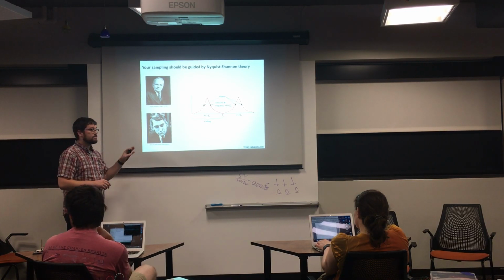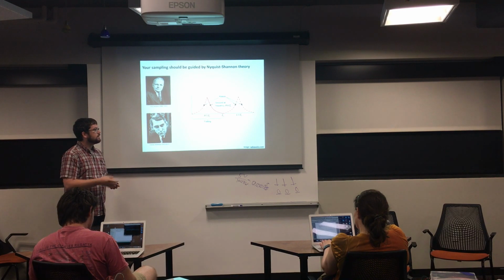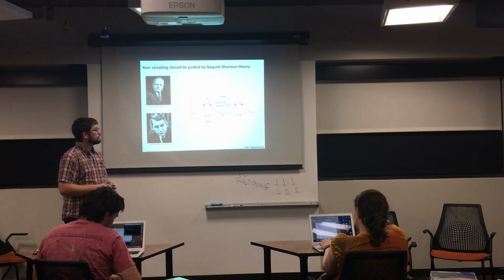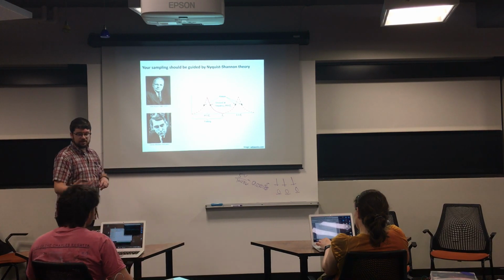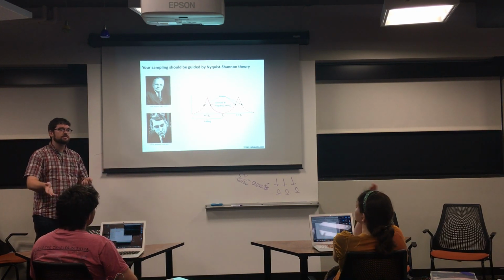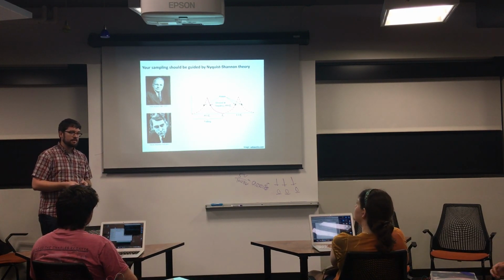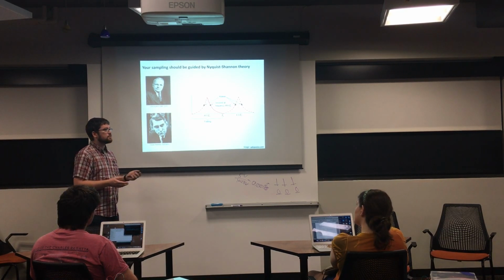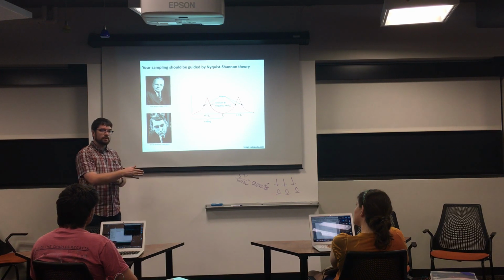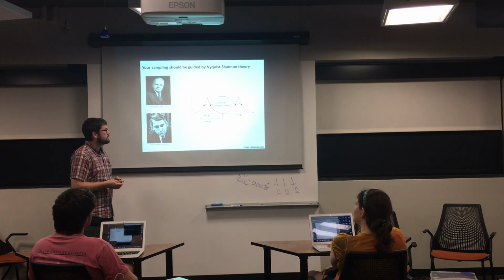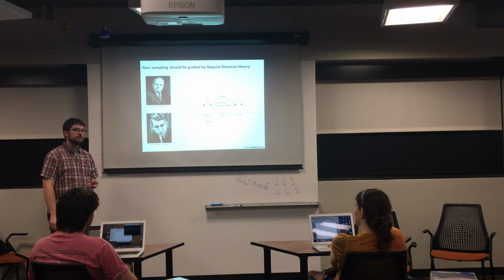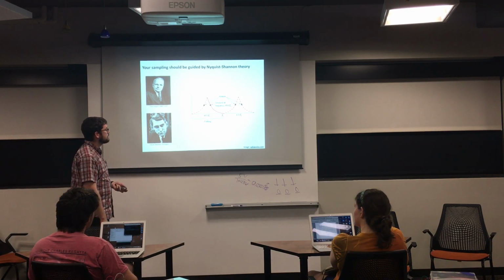One of the most common tactics we use is putting what's called an anti-aliasing filter in front of our analog to digital converter. So we know that we're going to sample at, say, 100 hertz from our Arduino. Then we would put a filter in front of it that would have a corner frequency, so it'd be a low pass filter of maybe 30 or 40 hertz. So anything above that would be significantly attenuated and not make it into our data.